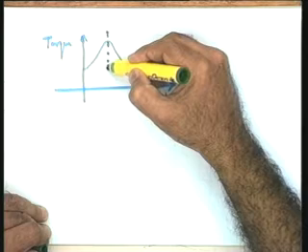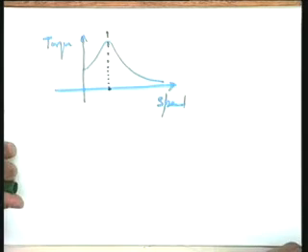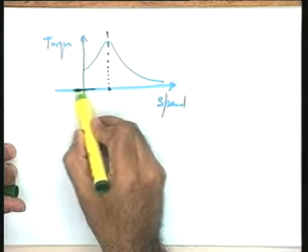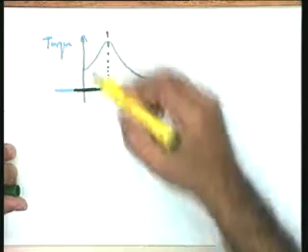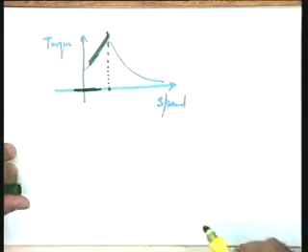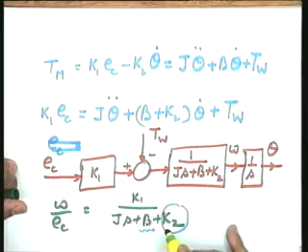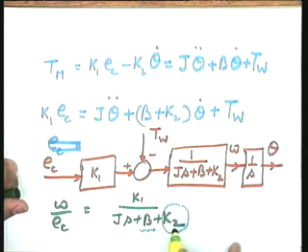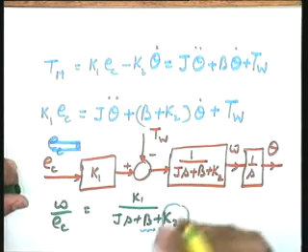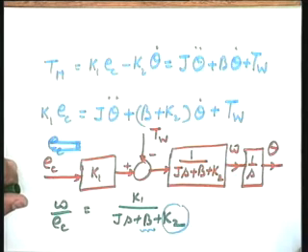B plus K2 may be less than 0. In that case, it will. That's right. The answer is correct please. In this particular case, you will please note that for an induction motor you are working at this particular speed, but for a servo application you are working in this region. So if the slope becomes negative, in that particular case what will happen? If K2 becomes negative, this amounts to negative damping, and negative damping, depending upon its magnitude in relation to B, can even lead to instability, or the hunting naturally will come.